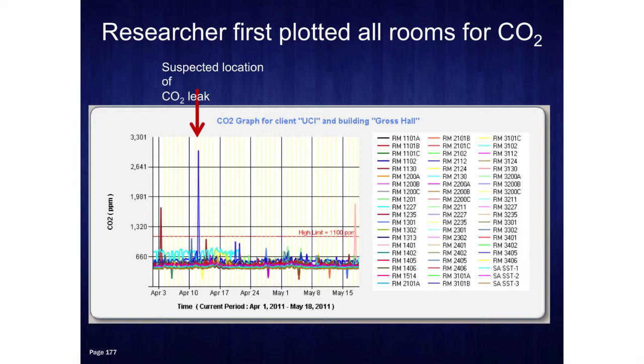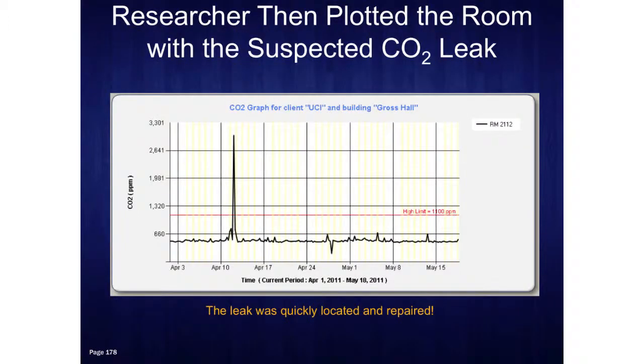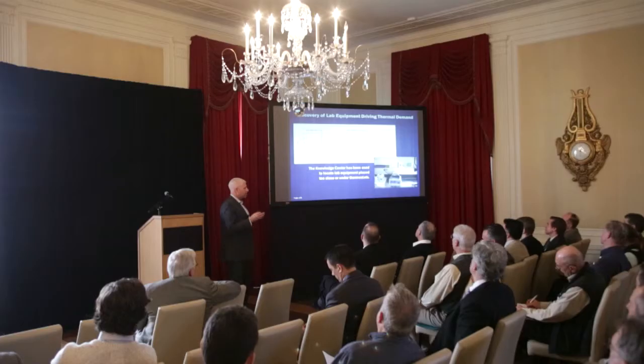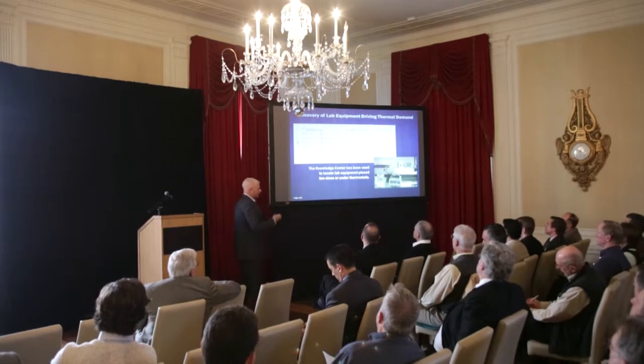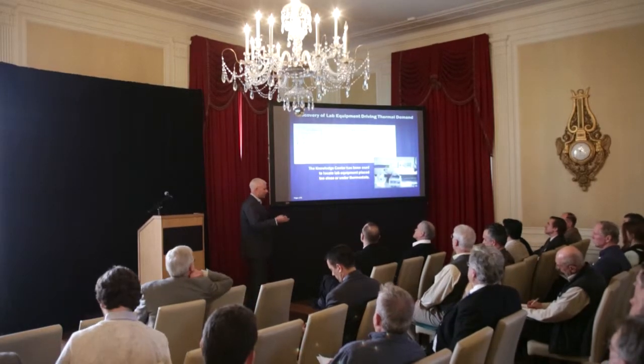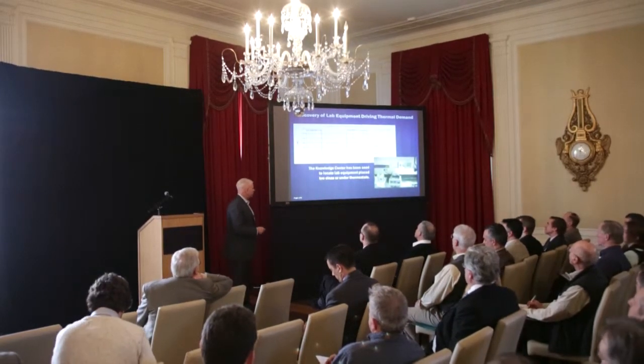So they did. And you can see, yeah, the colors are pretty tight and they repeat, but you can drill down in. You can figure out what room has the leak of CO2 from that system. Then they connect an air compressor, soap the lines in one room, identify the leak, fix the leak, put the system back in place. Another example, constant, that's not really commissioning at that point. That's just troubleshooting a building.